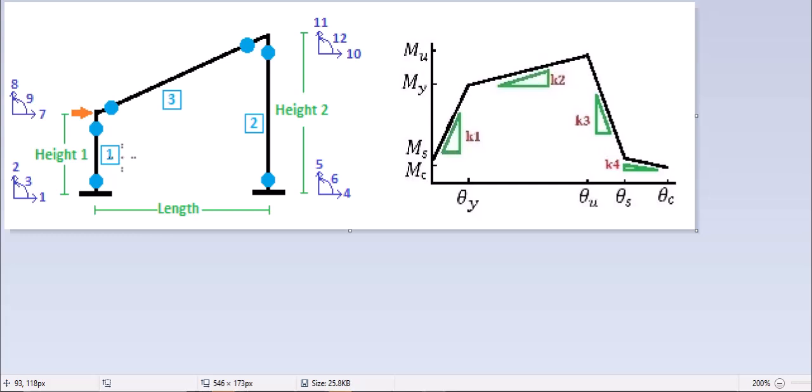So first of all, we didn't define the plastic hinge, but in each increment we are going to check the analysis, and if the plastic hinge happens in each section, we are going to apply it and define it, for example, at the start or end of this section element, and then run it again, and then push the other incremental force.